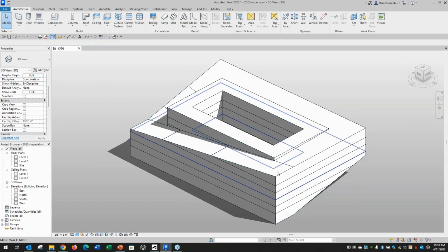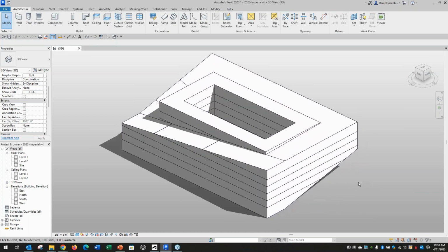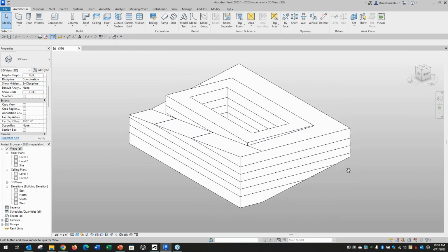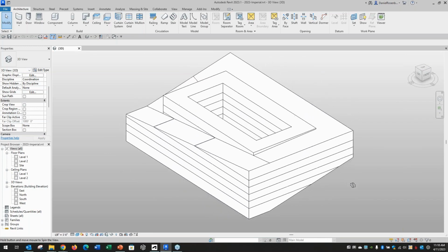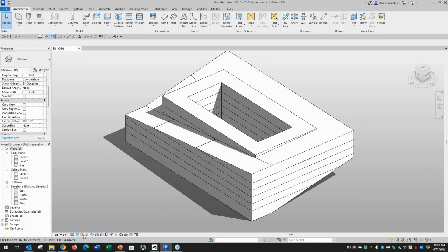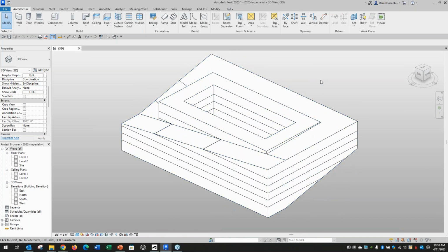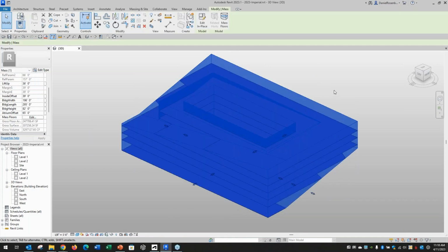All right, so what are we looking at here? A typical starting point for a lot of schematic design projects, or a lot of construction projects, is starting with some sort of building mass shape. And you might want to look at this and play around with it and flex it. And that's exactly what we have here. If I click on this mass element, you can see I've got the floors in here. Eventually this will be the form of my building, but for early schematic design, I might want to be flexing some of these parameters.